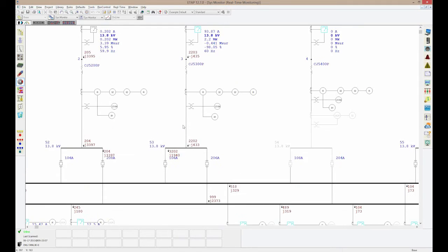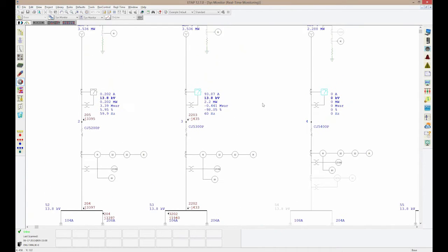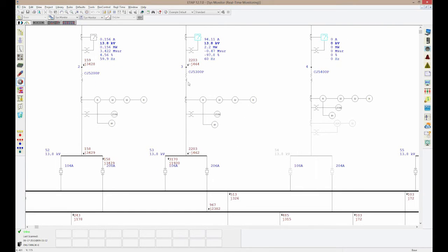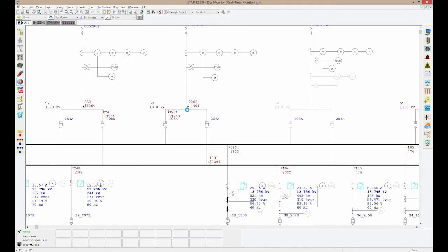And this circulation is actually being shown via state estimation. So utilizing the measurement that I have upstream on the generator, utilizing the model that I have previously built and used for various calculations like power flow and short circuit and so on, I'm using the same model to figure out what are the estimated flows throughout the system.